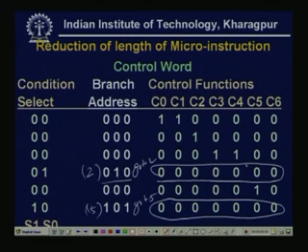Now, in a typical microprogram, there may be several conditional and unconditional branch instructions. Therefore, a lot of memory space is used inside the control unit. But what we have seen is that if it is a branch instruction, then the control functions generate 0 control signals. So, in practice the format of the control word is organized in a different manner to minimize the size. This reduces the implementation cost of the control unit.